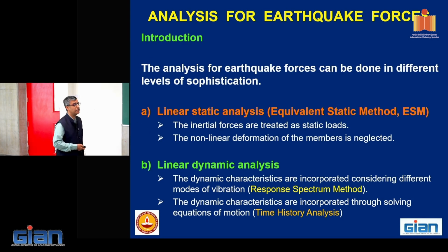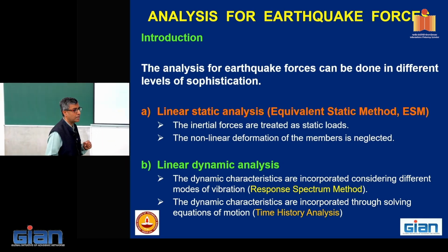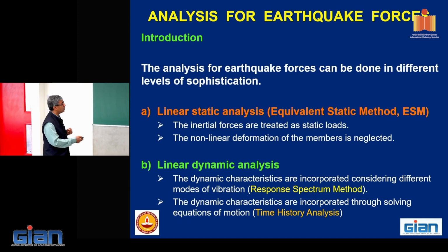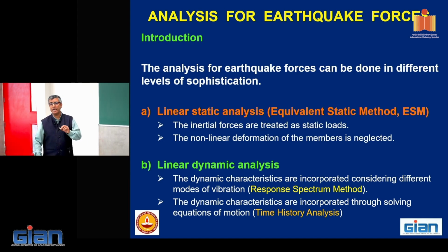Just like wind, we have different methods of earthquake analysis. The simplest one is the equivalent static method, where the inertial forces are treated as if they are physical forces acting at different levels. Please note, this is an idealization. Okay, someone has done this structural analysis, or I would say structural dynamics. From the inertial effect, we are trying to get these forces as if they are physically, statically acting. Conventionally, we neglect the nonlinear deformation. And how do we account for that? I will come to it later.